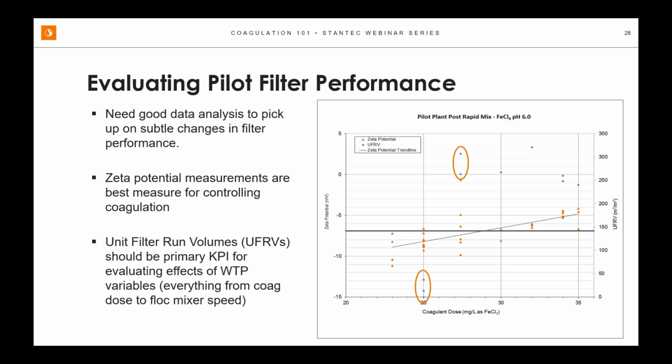In fact, some of the plants that I know of that have used zeta potential a lot, they say, as long as we're between -5 and +5, or -5 and 0, or -7 to -3, things work. So that is a fact of life. After doing this a long time, I don't have a good explanation, but it's a reality.